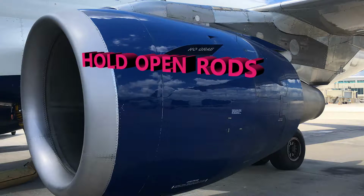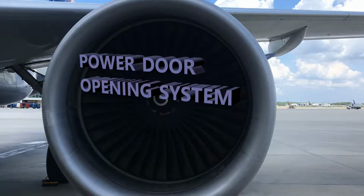And the power door opening system is obviously helping with the opening and closing of the cowls. As far as what components you have with the PDOS, okay, you have a power pack. You also have the actuators. You have 2 fan opening actuators, as well as a set of the 2 thrust reverser opening actuators. You also have switches and a fan cowl proximity switch. Okay, so those are your actual components.